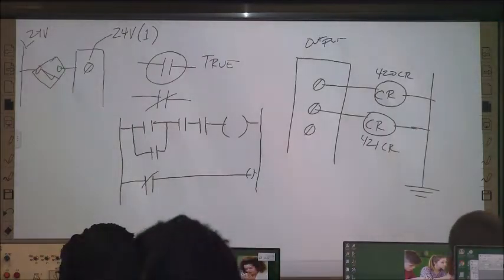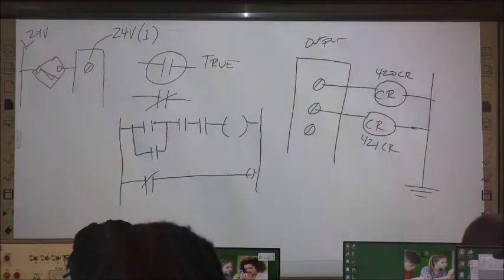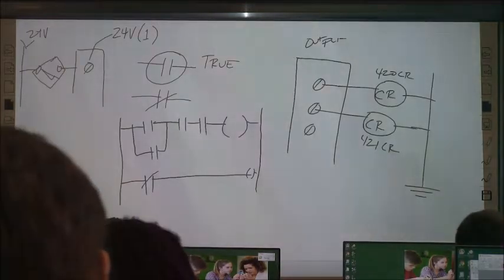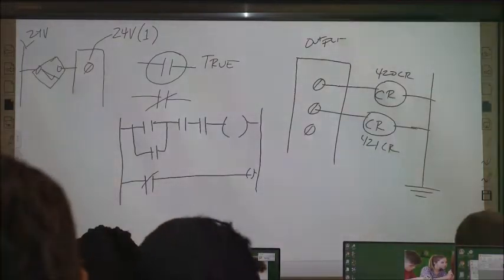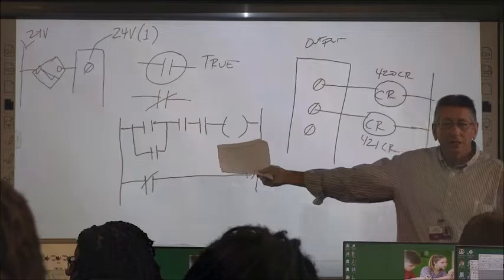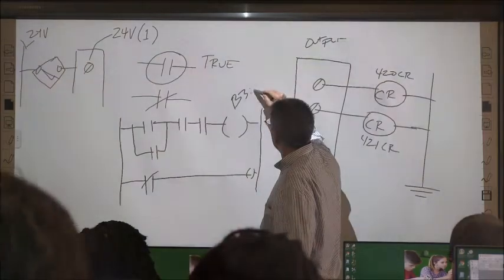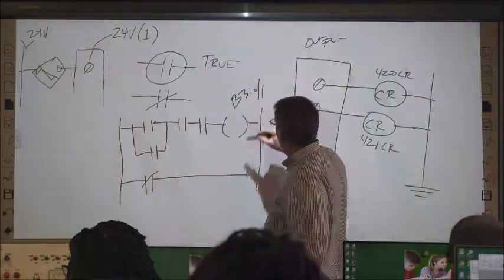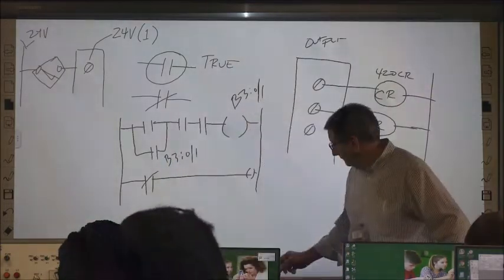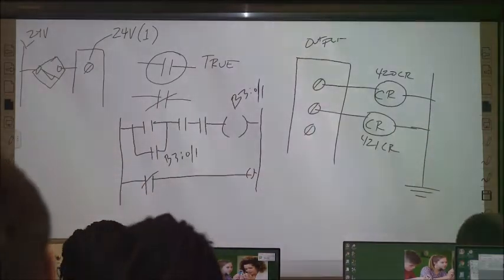And another part of this, you need to understand how the relay logic works too, right? You've got to go through it and figure out how the relay logic works. Does the control relay logic make sense? Here's the control relay. We have a seal-in. So if we're energizing this, here's our PLC logic. The very same logic as the hardwired logic.